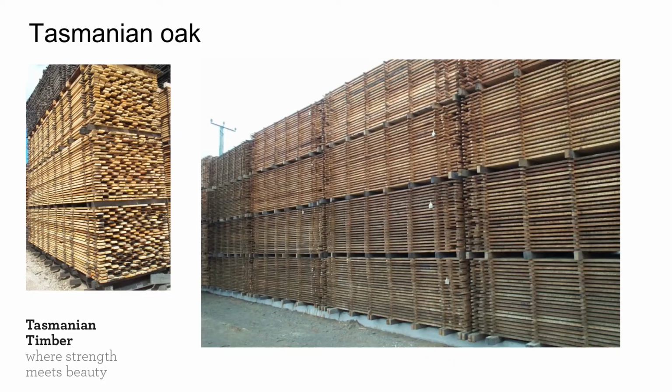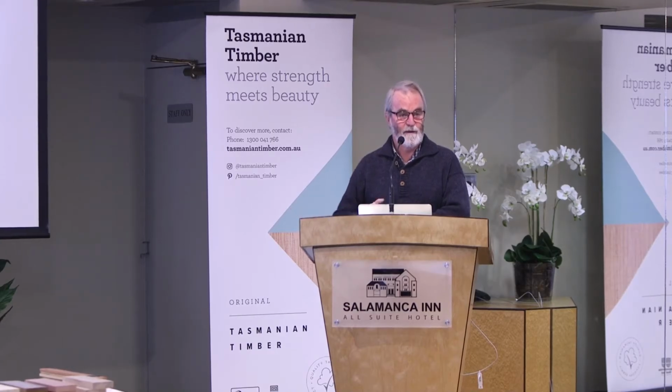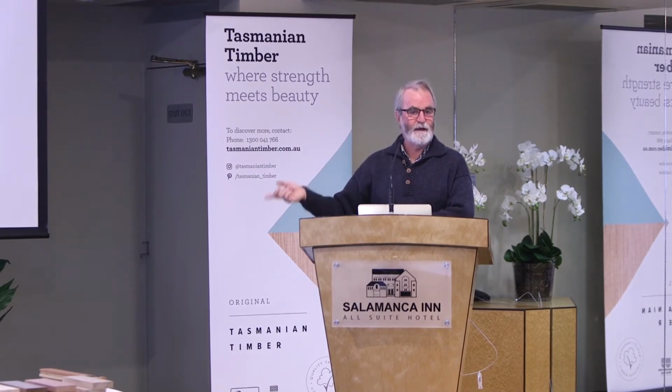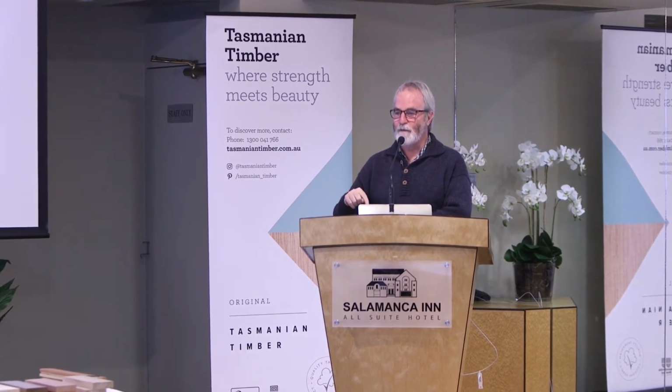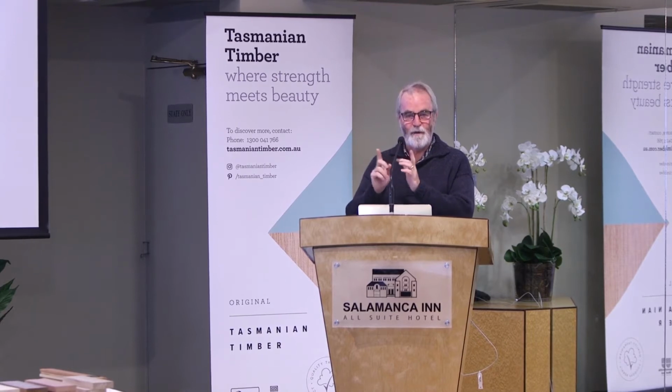But interestingly, one important thing I'll bring up, which I'll explain again in a bit more detail later, is that if we measured that rack, when we put it out, we'd have a particular height. If we come back 3 months later, it's going to be 50 millimetres shorter, because the wood's going to shrink as it dries. And that's really important for us later on when we design something, because it doesn't just do it here, it does it too when we put it in the building at a particular period.